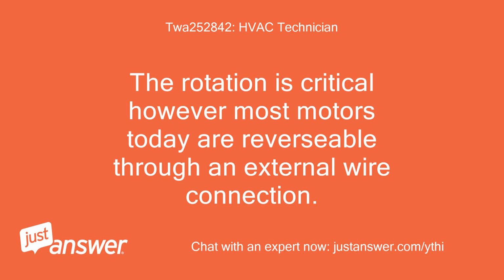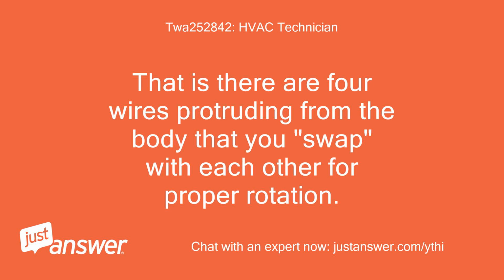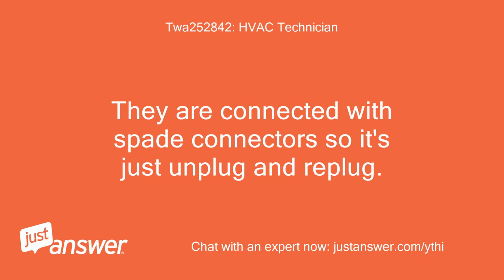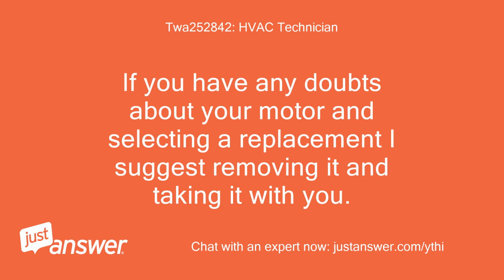The rotation is critical, however most motors today are reversible through an external wire connection. That is, there are 4 wires protruding from the body that you swap with each other for proper rotation. They are connected with spade connectors, so it's just unplug and replug. If you have any doubts about your motor and selecting a replacement, I suggest removing it and taking it with you.